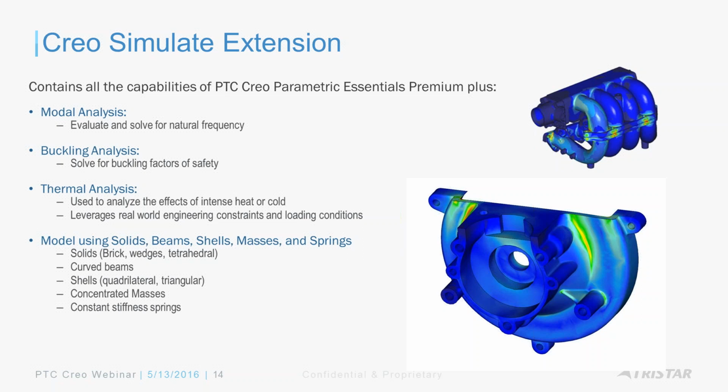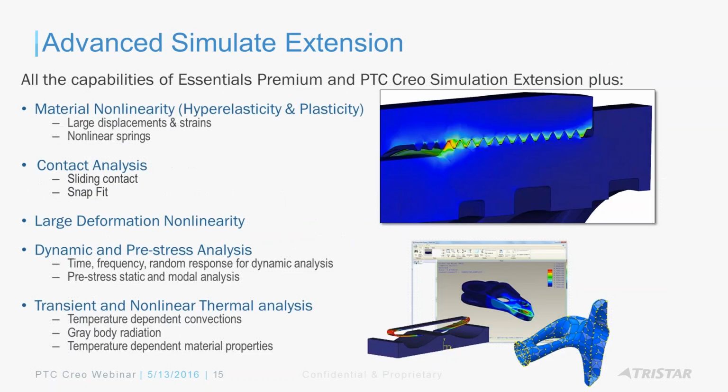Or if you have huge structures, right, you could just use beam idealizations. And all these are computationally less expensive compared to the actual CAD model that you may have, right? So that's when you would need the Simulate extension.